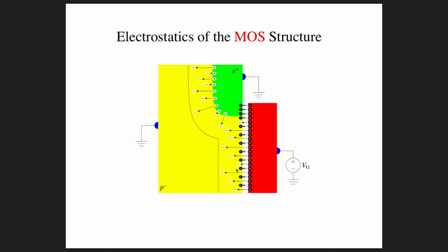So we have weak inversion being synonymous with subthreshold. We have moderate inversion being synonymous with peri-threshold or around threshold. And then we have strong inversion, which is correlated with above threshold. Okay, so remember, the threshold voltage is basically just a special gate voltage at which the depletion region depth underneath the channel first becomes equal to the depletion region depth underneath the source region here, so that there is practically no energy barrier between the source and the channel region at the surface.